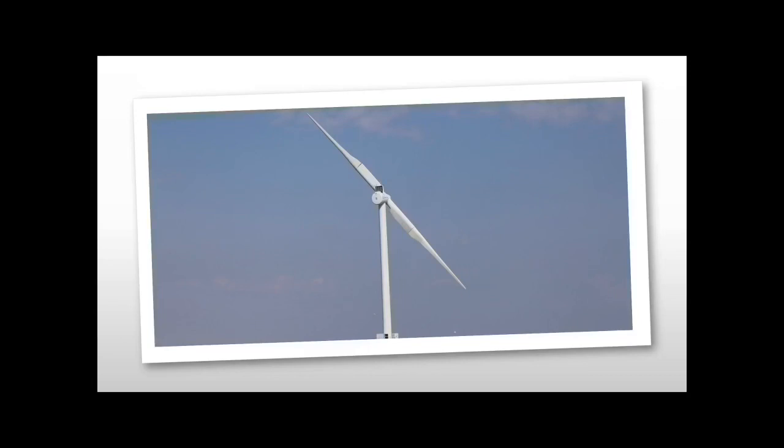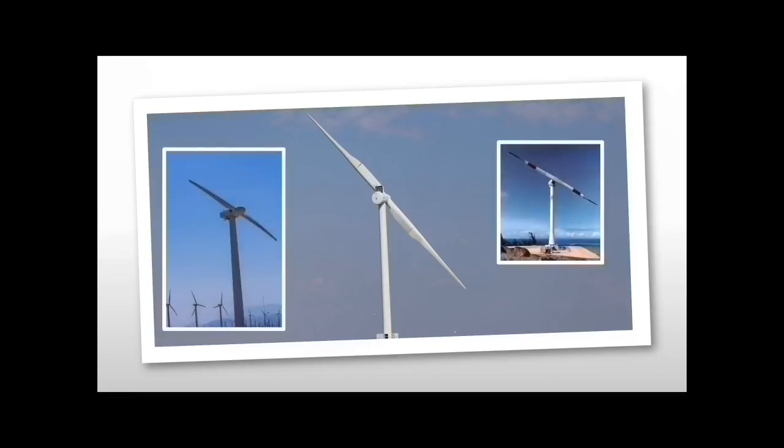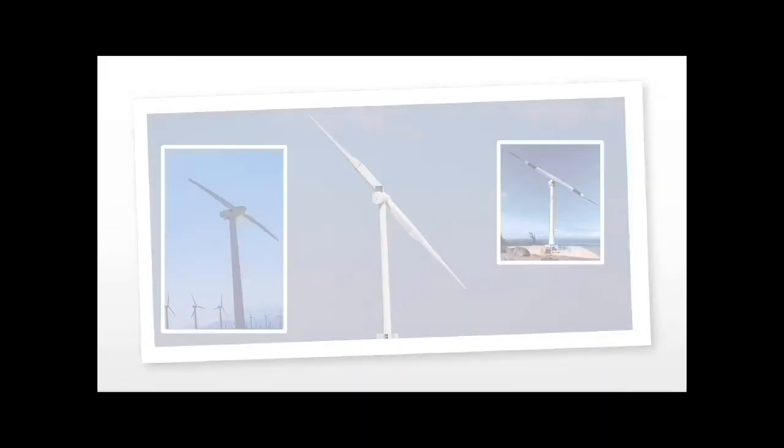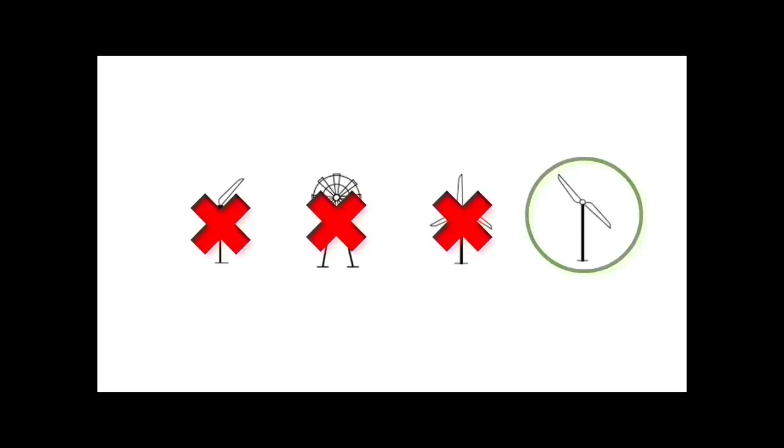However, for smaller non-commercial applications where wind velocity is rather small, 2-bladed turbines prove to be more suitable. Studies for small-scale models show that a 2-bladed turbine yields more energy than a 3-bladed one, as there is less interference from the blades. Moreover, a 2-bladed configuration will also make the turbine fit better within the dimensional constraints. Hence, a 2-bladed design was chosen for our application.